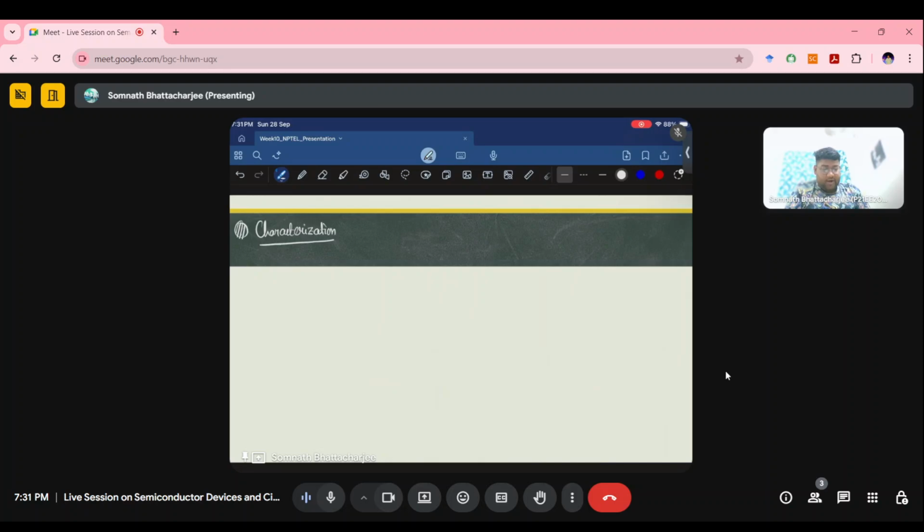These devices are directly characterized by connecting the gate, source and drain terminals to an SCS, that is a semiconductor characterization system, or also an SPS, semiconductor parametric system.